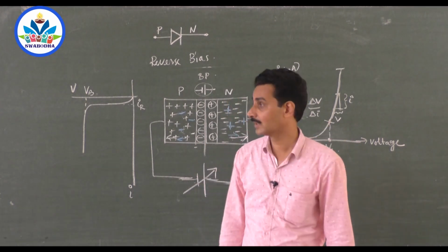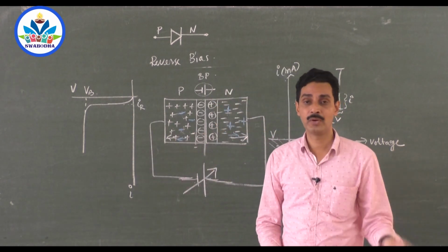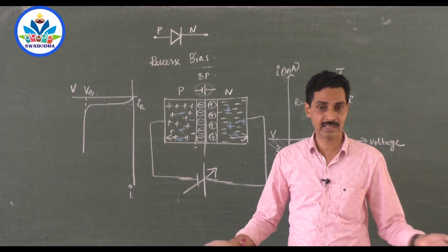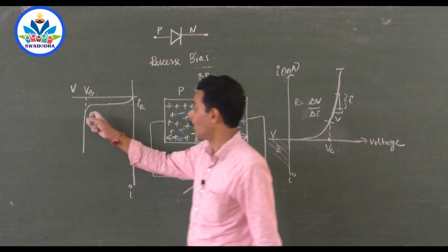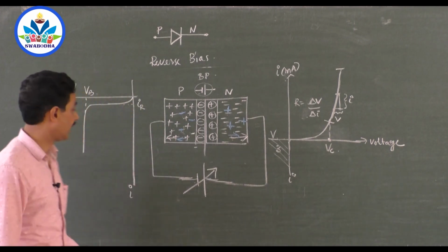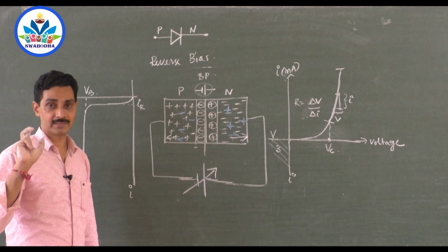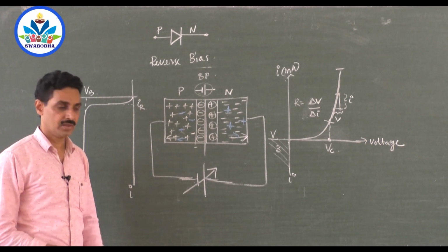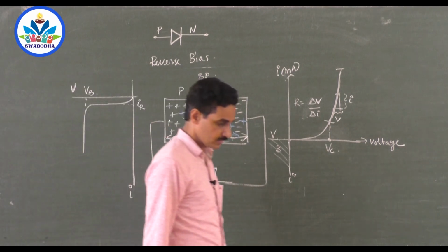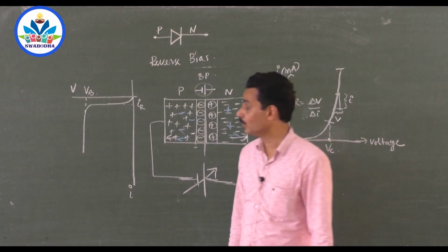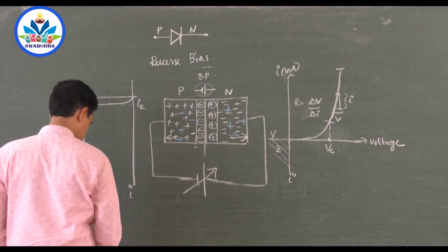If you go beyond the breakdown voltage, there will be a breakdown and the junction breaks down and more free charges will be created, and it cannot be repaired. It is an irreparable process. Once the breakdown is reached, high current flows, because of the breaking of the atoms or molecules. So many electrons and holes will be created, so they cross the junction. But imagine that we are working with only this much.